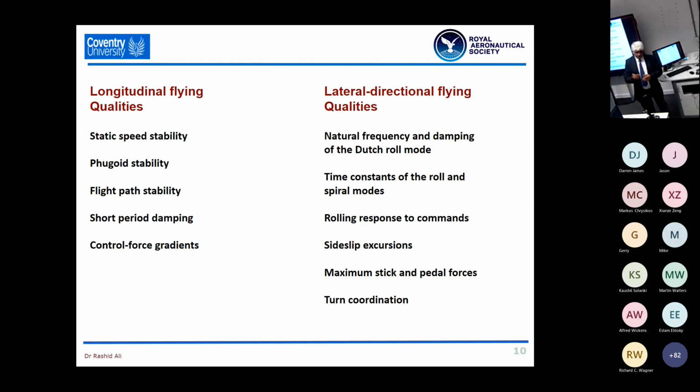So, for example, it goes up, then starts to increase in speed. As it increases in speed, it gains more lift, it then climbs up. So it has an oscillating behavior, which is long-term. Now, it can be quite troublesome. Most aircraft will exhibit that motion, some a little exaggerated, others not, as the case may be.